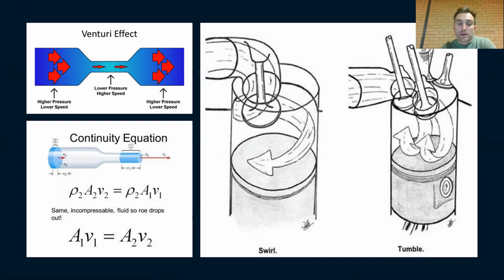The turbulence inside the combustion chamber is referred to as the swirl and tumble ratio. If we increase the ratio of both swirl and tumble, this will help maintain the atomization of the incoming fuel particles rather than allowing them to form back into droplets. This results in a more homogeneous air-fuel mixture, which greatly increases the efficiency of the combustion process, and more stable flame propagation, reducing the effects of knock and detonation.